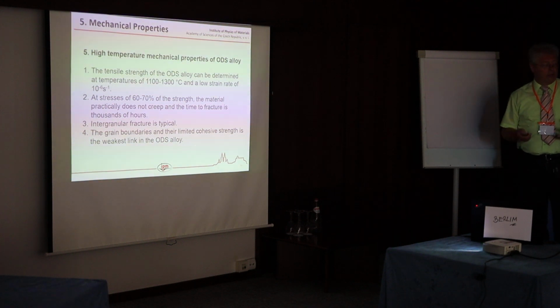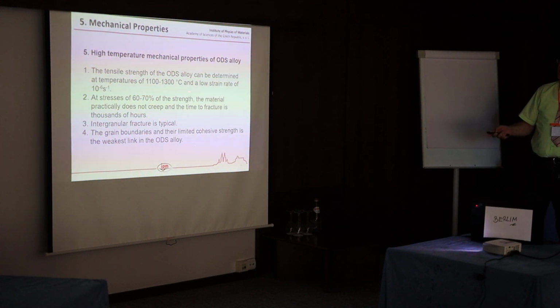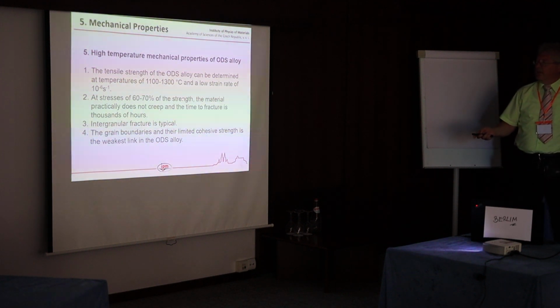And now we can look at the mechanical properties. We basically tested with a very slow tensile test at 10 to minus 6 per second strain rate. And when we put the material to the creep test at about 60 to 70% of this measured value, it practically doesn't creep.